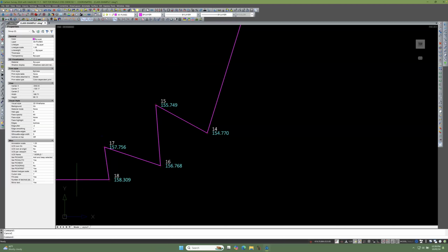And then they would draw the property boundary, say through point 17 to 15 or whatever. Well, if that person is used to using it, but then I get the file and I'm having to work on stuff and my settings were done. So I would draw the boundary, say 17 to 15, but I had the linking turned on. And it goes back to this other guy who has his linking off.